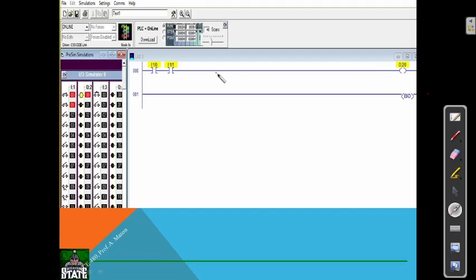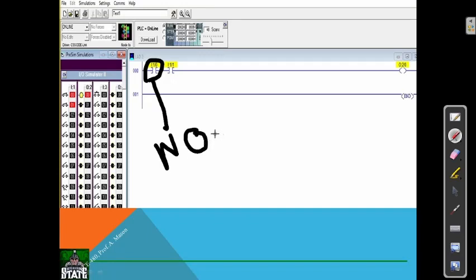No, it won't glow. Because this rail has a supply over here. If I switch off this switch, then there is no connection between here and here, because this one is off. As I said before, this is a normally open connection, an NO connection. NO means normally open. If it were normally closed, we would have supply over here, but it is normally open.